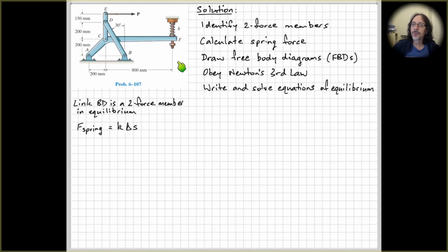So next thing we want to do is to calculate the spring force. Now the reason we want to do this now is because this is our only input force into the problem. Right? So we're told that we need to work out this force here, P. So the only way we can work out an actual force to use in our calculations is to work out the force that's generated by the spring here, by the compression of the spring.